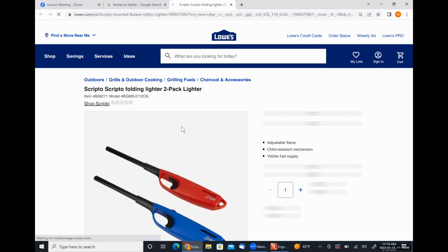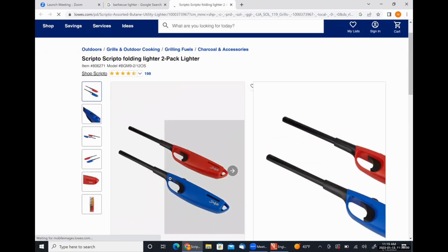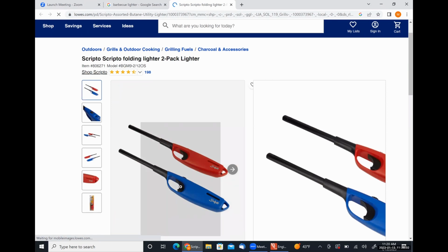Yeah, so this is the type of lighter that I'm talking about in particular, right? If we were to take this thing apart, this trigger is acting on a spring, which is storing energy, and it's literally a little piston that once you pull it far enough, it gets released and it smacks into this crystal. The crystal has electrodes on both sides of it, and wires that literally run all the way down the length of the barrel.